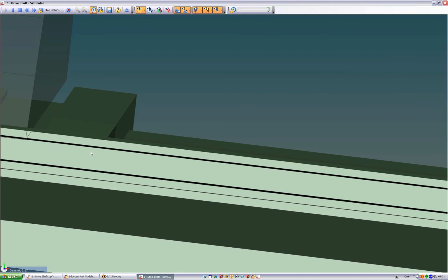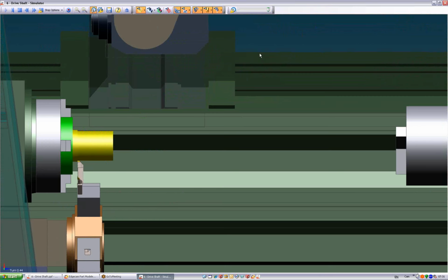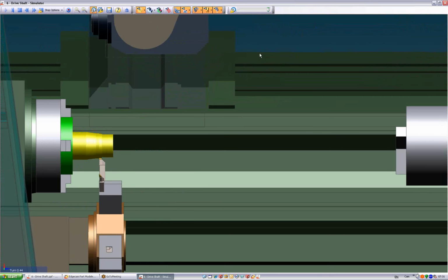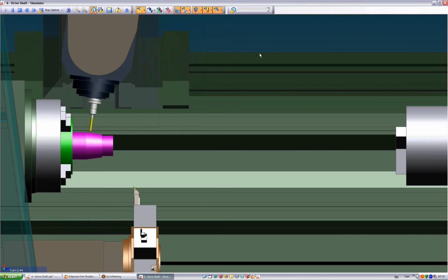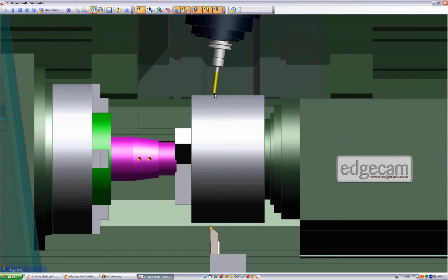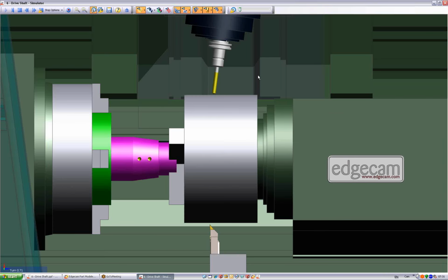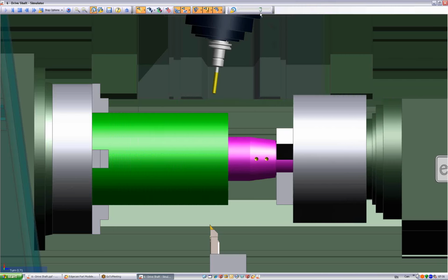And again, I'll just zip this across into the simulator, where again we see solid models playing a role, because of course solid models are used to build up the machine tool kinematics. We see some lower turret turning, upper turret on B-axis now. This is why we need these sort of tools. We don't want to crash the end of that tool onto that chuck, so this is why we need that machine tool simulation so much.